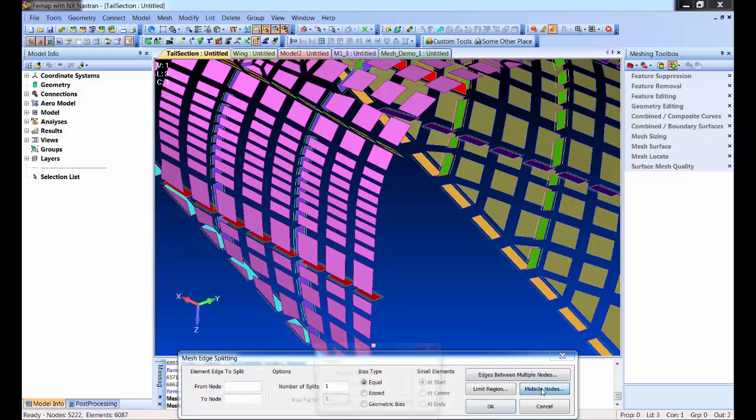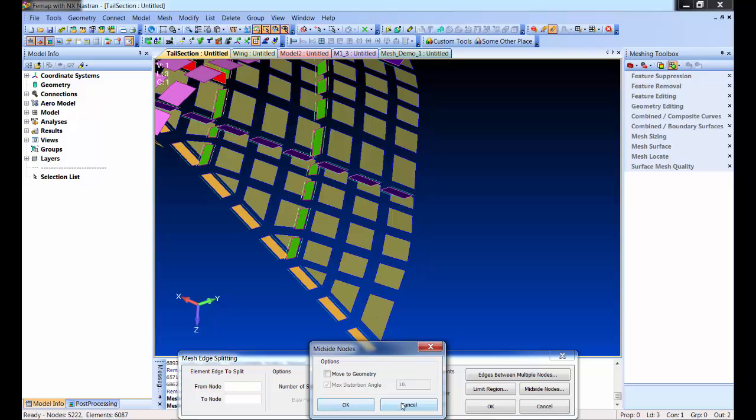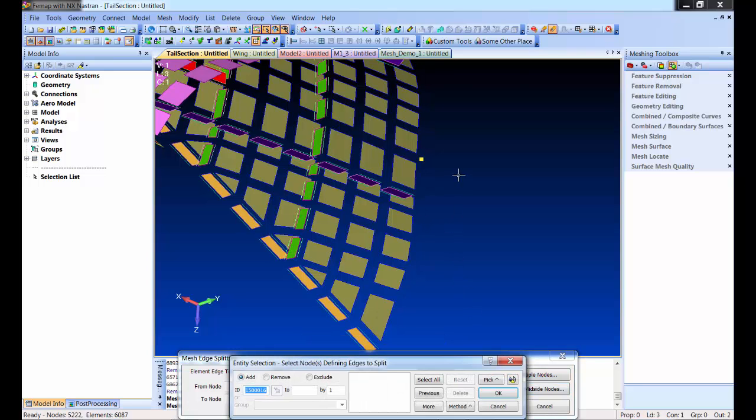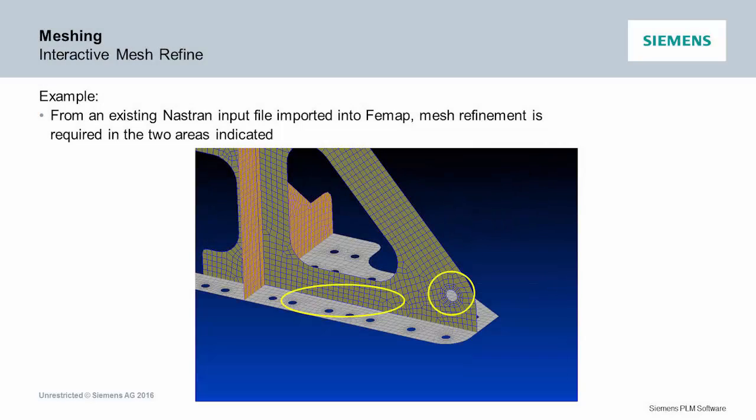And this one in version 11.3, we added a multi-pick too. So if you were kind of doing that, multiple nodes, you can now pick multiple. It'll go through and do them at one time. And this does the same thing, splits the beam, properties, pressures, constraints, anything. Just another quick example, T-junctions, whatever's connected is going to stay connected. It gets it all done.